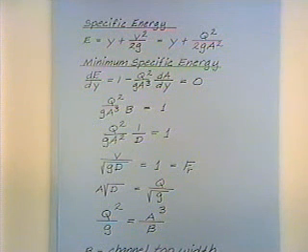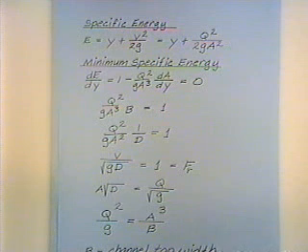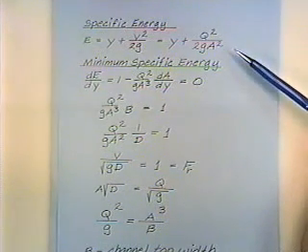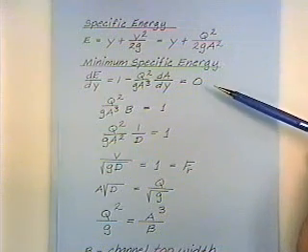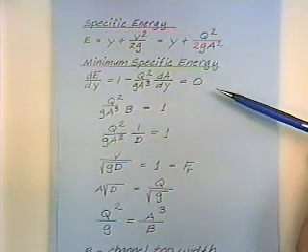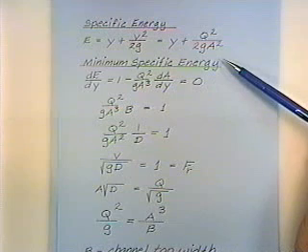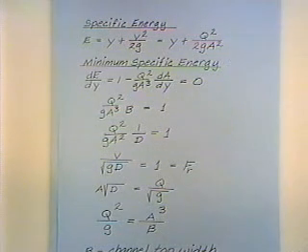You can write the velocity head v squared over 2g, or recognizing that the velocity is the discharge divided by the area, you can write it Q squared over 2g A squared, just plugging Q over A in for the velocity. And so if you wanted to find the depth at which this expression's a minimum and to derive the equation that we'll be using, you would set the derivative of this expression equal to 0, and then just reduce it down.